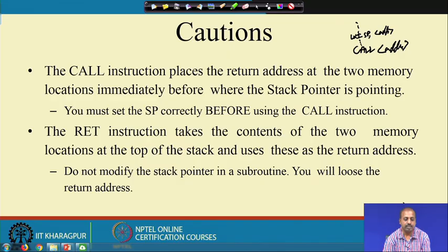Similarly, the return instruction takes the contents of two memory locations at the top of the stack and uses these as the return address. So, we should not modify the stack pointer in a subroutine. If we modify the stack pointer in a subroutine, then this will be lost.